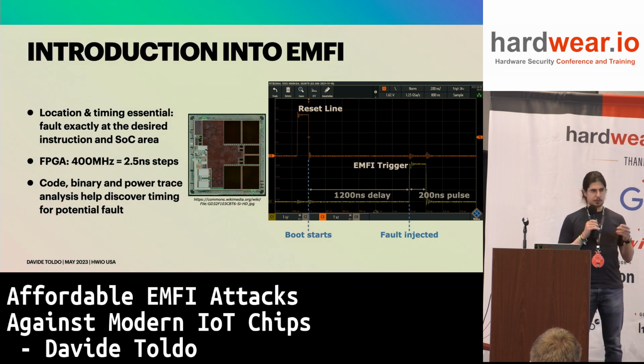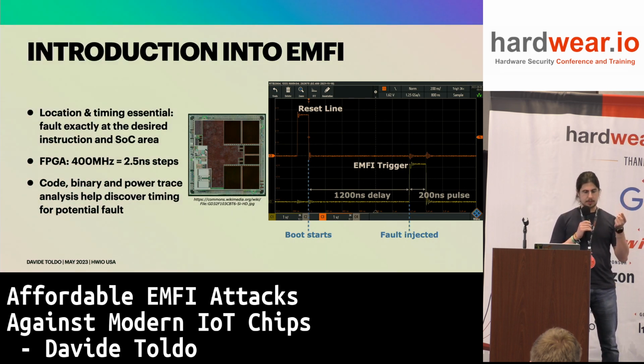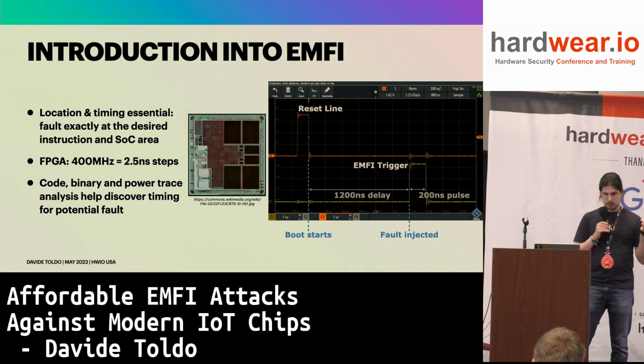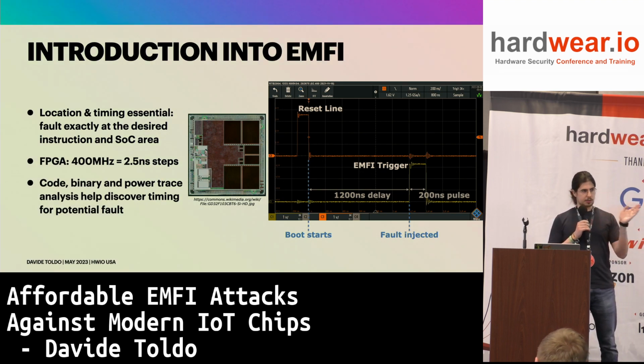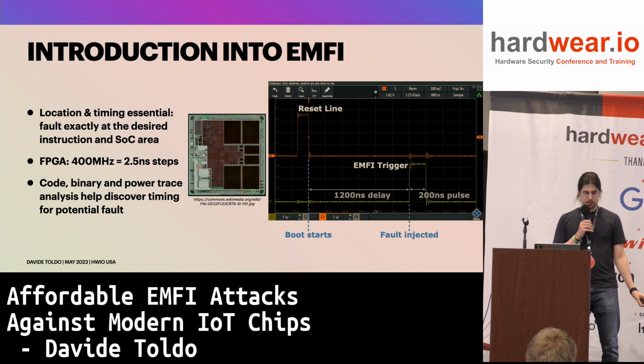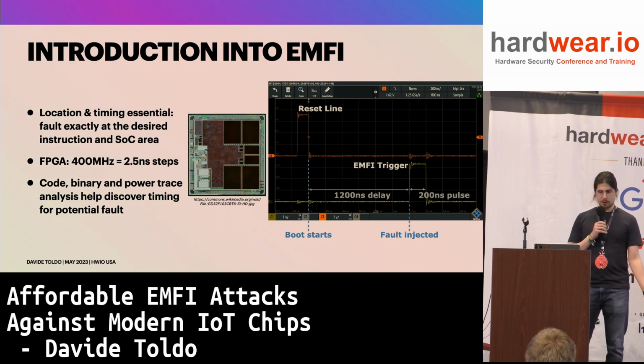For EMFI both you need good timing and good location. You need the right instruction, of course, so you need the right delay from a certain known signal, like a boot time. And also you need to find the affected SoC area, which you can fault.